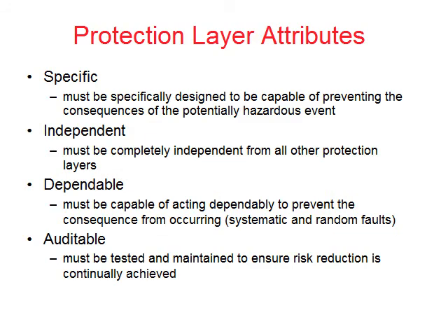Now, a SIF is a specific type of independent protection layer. And an important thing to remember as you're looking and designing these things is that there's four tests a potential function has to pass to be considered an independent protection layer. First, it must be specific. That means that it's designed and capable of preventing the consequence of the potentially hazardous event.